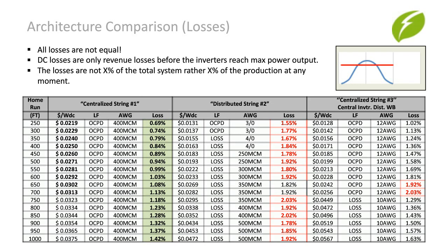But AC loss is a little different. The AC losses are directly related to revenue loss. The inverter has already converted the DC, so those losses aren't fixed by raising the DC to AC ratio, but a similar curve still applies. At 9 a.m. on a south-facing array, we are not producing max power. A 1.5% loss on a 1 megawatt array is not 15 kilowatts at that moment. It would be 1.5% less the power the inverter would be producing at the moment based on the DC input power, which is much less than peak.